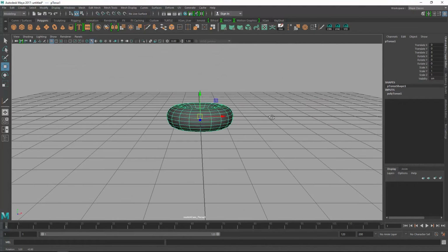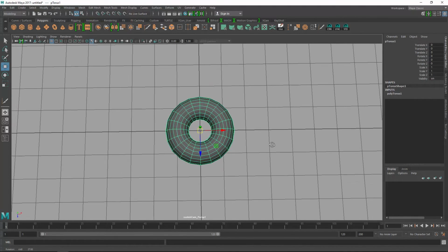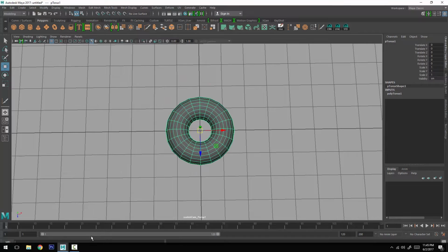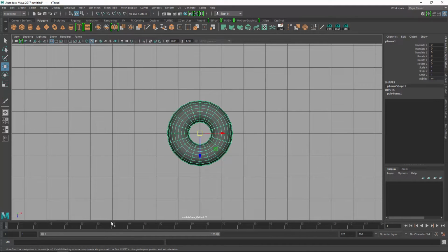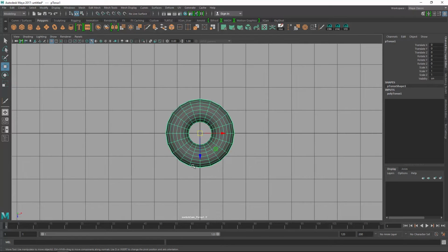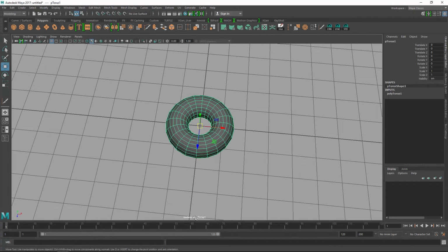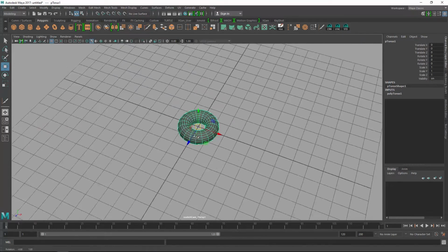What the switch cam script does is, if you're near the top view and you enter switch cam space 1, it creates an orthographic camera. And if I type that again and hit enter again, it goes back to perspective, but now it's switch cam perspective.